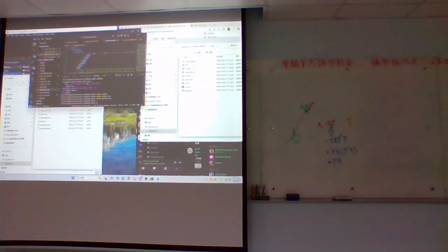So how would we process that? Let's say you want to first write a routine that prints out all the important information from the MuJoCo XML file, which means you want to print out every part of the body line here, and every part of the joint. Those are the two types of entries we're interested in to calculate our forward kinematics.